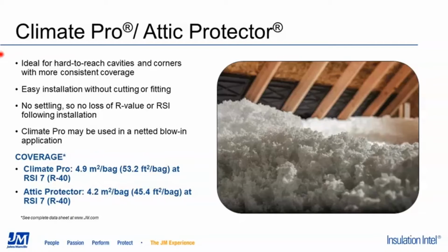This is blown into an attic most typically at a certain thickness for a given R value. Another application is that you can use it as a net and blow in walls, where you put a mesh fabric over the open stud cavity, put a hole in that and fill that cavity with loose fill fiberglass. Does a tremendous job of filling every nook and cranny to get that solid installation. But most times this material is going to be up in your attic.